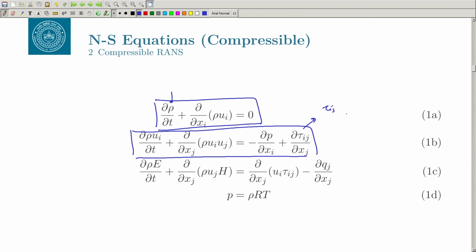Okay, and then you have the additional energy equation, right, which is shown here. You can write it in thermal energy or total energy. What I am showing here is the total energy equation. This is the total energy where H can be given as E plus P by rho. Okay. So, this is your internal energy, and this is the pressure energy, right, and then you have this enthalpy, where E is just e plus K. Okay.